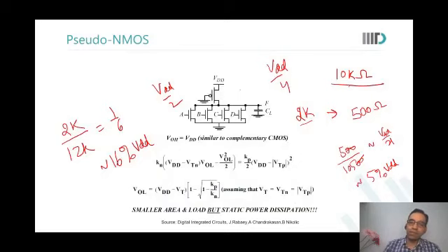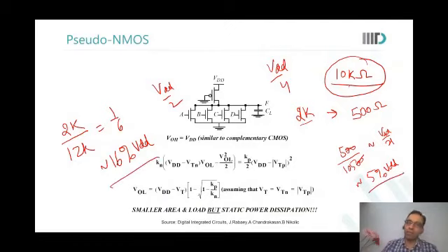In the earlier case, we saw that if I keep the PMOS very resistive, my rise time would be very bad. The 16% and 5% is fine, I'm not worried. So to get a good rise time, what do I want? I wanted the PMOS to be 2K. But with 2K, this was the kind of values I was getting on my output. Unacceptable. So what to do?